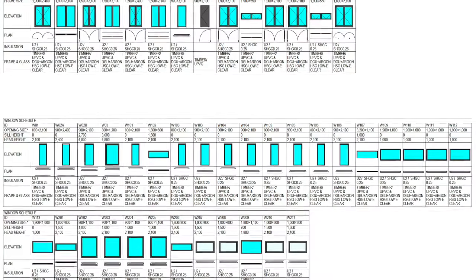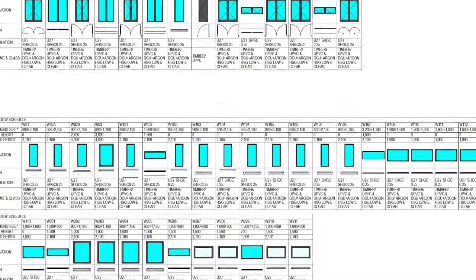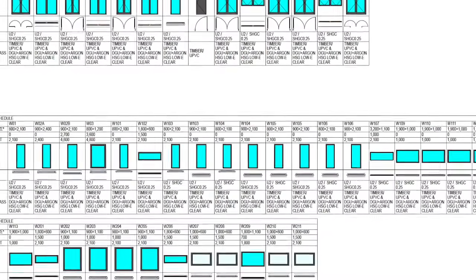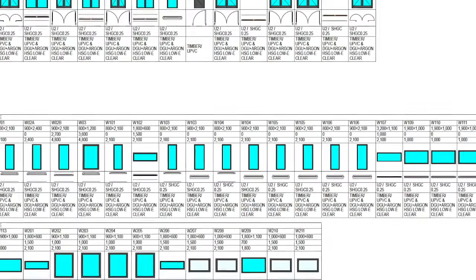In addition to all these other drawings, we may also need to show some schedules. Typically for DA, we need to convey some information about the doors and windows. But we need to at least give enough information to explain the DA requirements of the doors and windows. Now, this is already achieved partly through the BASIX or through the NatHERS assessment. The door and window schedule therefore is validating that or maybe providing that relevant information.